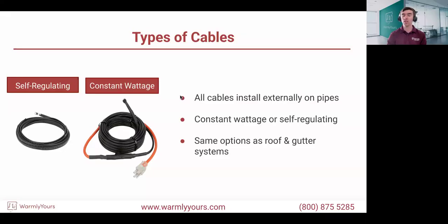You're not going to get to any situation where the cable is there, somebody gets the snow retention installed, drills or damages, or does something to the cable. That's like number one obvious thing for me personally. But after your snow retention is in, then you have the final route to get that cable installed and secured properly. So snow retention first, and then continue with the heating system installation.